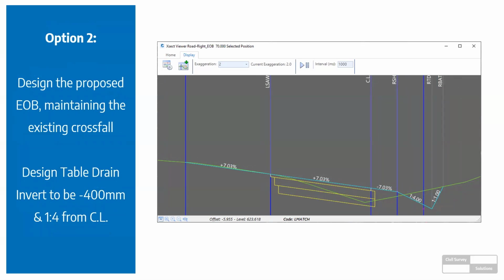In this case, the point of control, or the start, or the center of our design is actually going to be along the edge of bitumen. And we'll talk about this in a second. But we're actually going to be designing along the edge of bitumen and then putting codes out to the left and then codes out to the right. So a different approach, and there could be good reason for this.